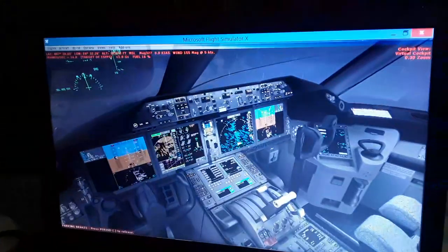So we have the aircraft, and we have the takeoff gross weight of the aircraft that includes the empty weight plus the passengers plus the cargo plus the fuel on board, the trip fuel, the reserve fuel and the taxi fuel.